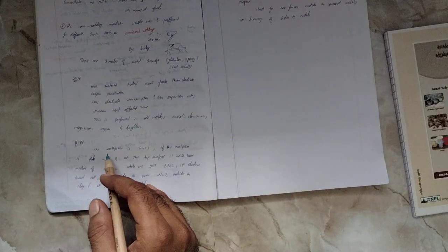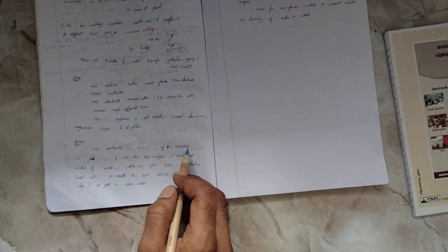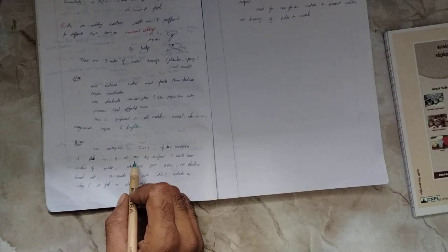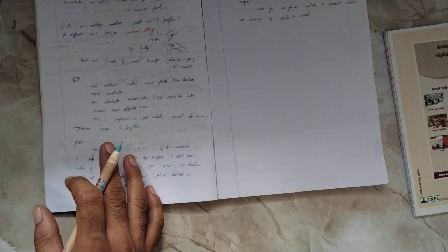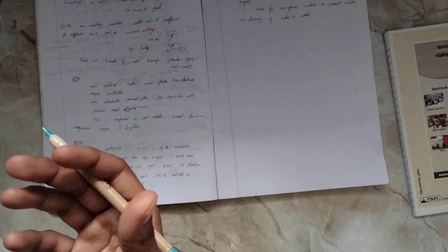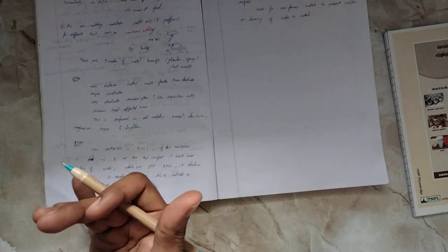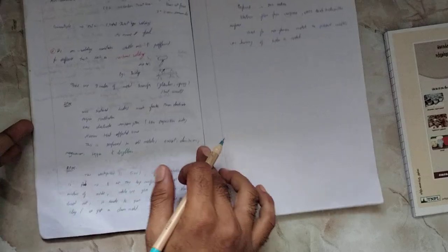So next you can see reverse polarity. In this reverse polarity, the workpiece is negative, and if the workpiece is aluminum, definitely the workpiece is negative, because the electrons tend to come out of the workpiece. What will happen is it will remove most of the oxide present in the outer layer. So it will remove the outside oxide.